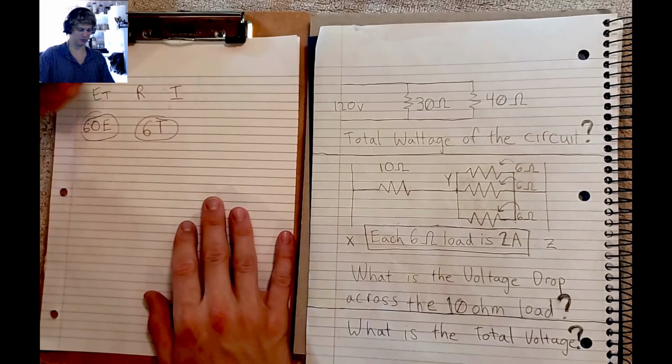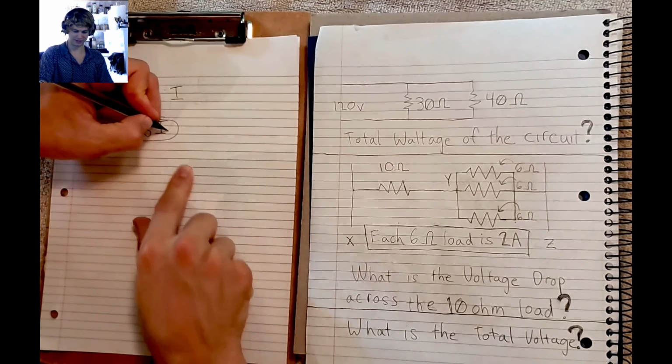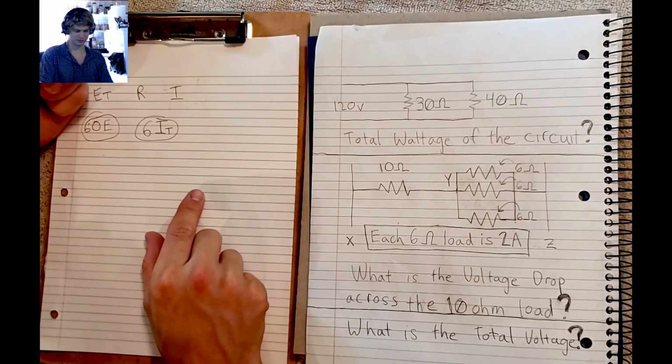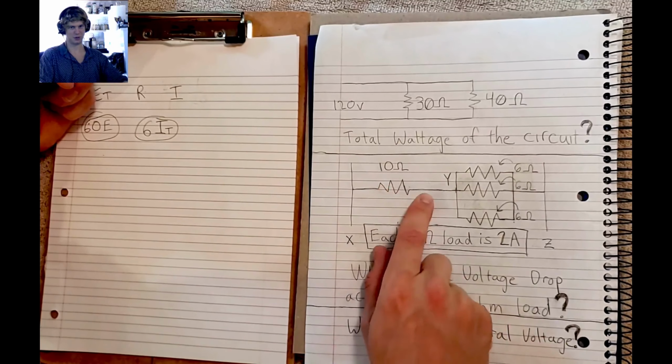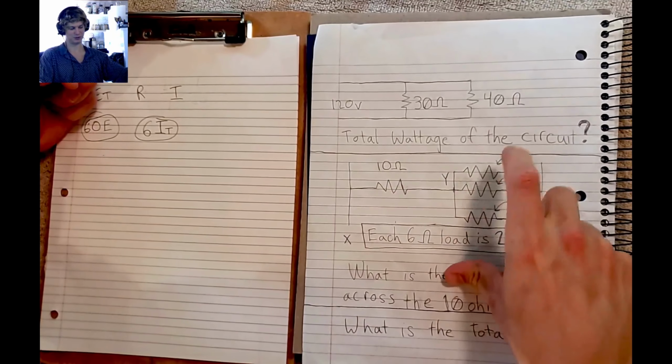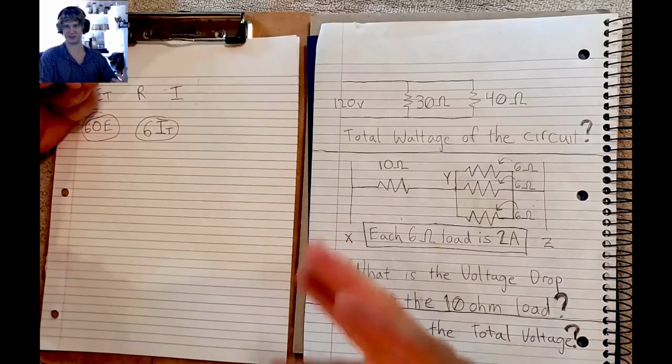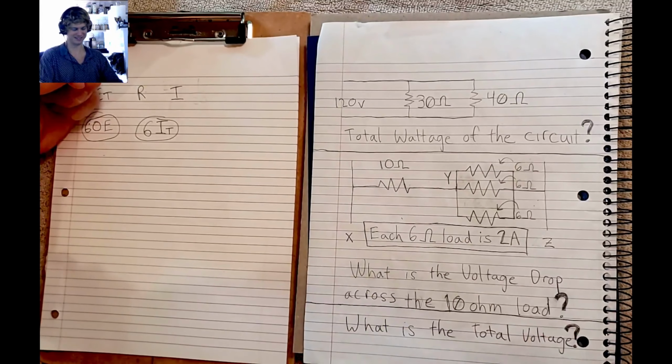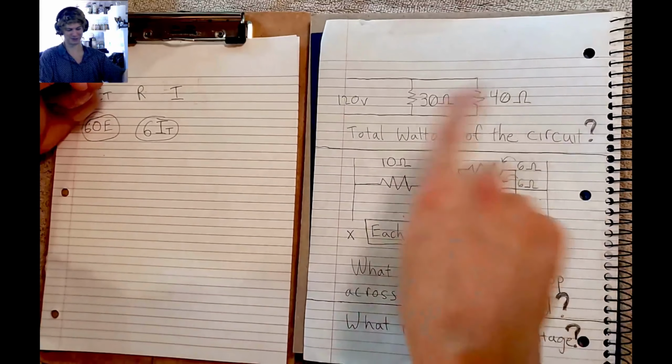I'm just showing you what happens when you do the reciprocal. So we have 6 I total. Of course, since this is wired in series and it's connected to these wired in parallel, this total current is going to be the same as this. I know I keep saying that, but it's good to really repeat these things. So we have 6 amps through everything.